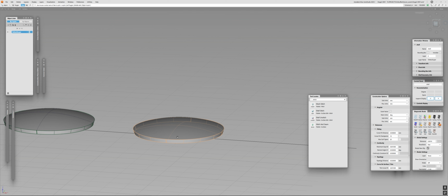I already mentioned it before, you need to create a matrix for that. And the matrix works based on the offsets. And they're supposed to be extremely accurate. That means that it is just a whole new level of complexity and pain. Luckily, these days, almost all the manufacturers take it under their control and do it themselves. But sometimes there can be situations where they go back to the design bureau and say, no, the matrix is just on you as well. And that means that you will spend more time doing offsets and matrix and die than actually building the model itself. This is the reality of the industry.